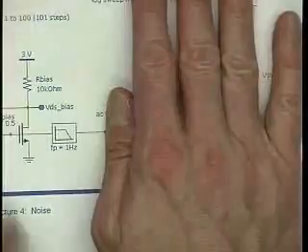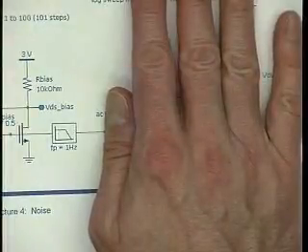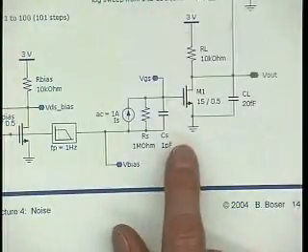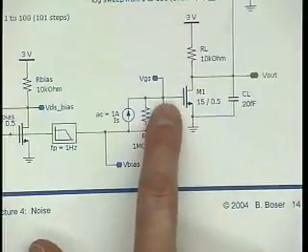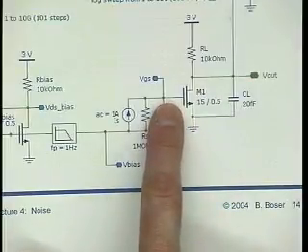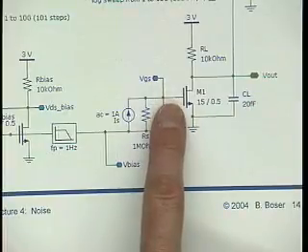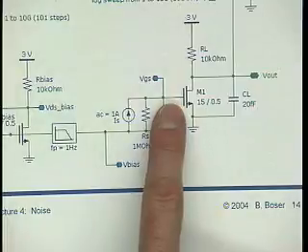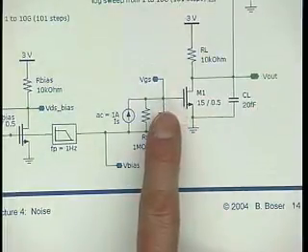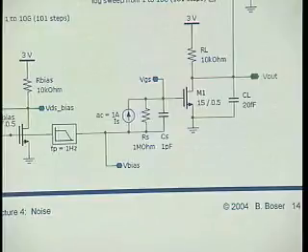This part here is simply for biasing. We've seen already that with a common source stage, we cannot just set the gate or input voltage to 0 DC-wise, because then the transistor would be off and gm would be near zero, and it wouldn't work very well. So we have to set this to just the right voltage, and there are lots of ways to do that. One of them is to run a .DC analysis and figure out exactly when the output is mid-rail, and write down that voltage to many digits.